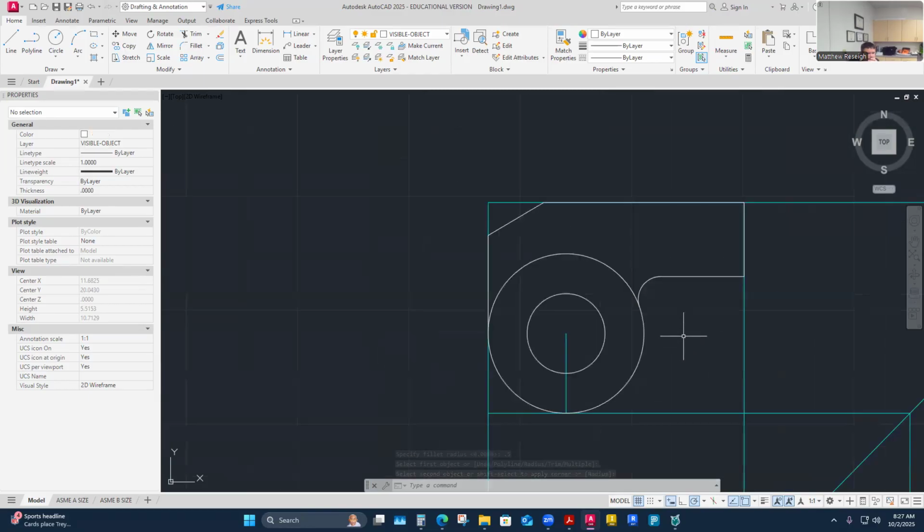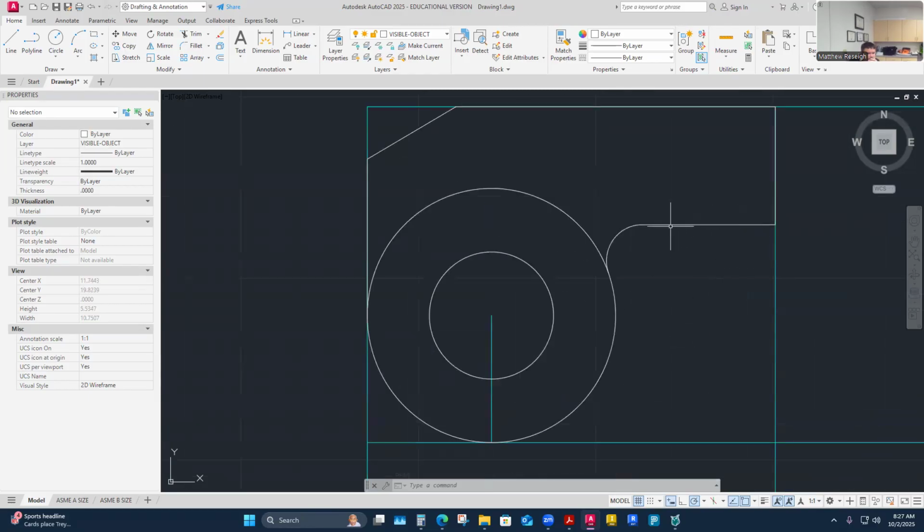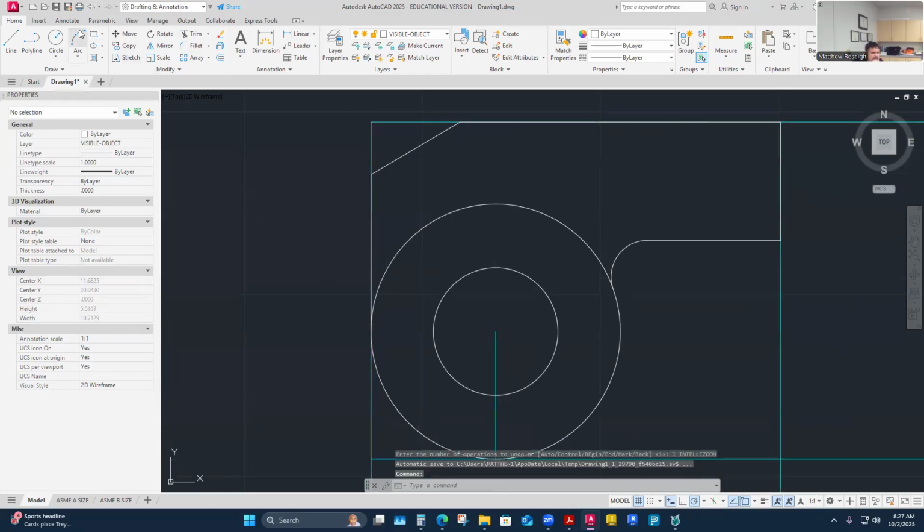So where I would hesitate on this is it really makes this like an S curve. And I feel like from center out, I should have some straight section and then pick up the radius. So in this case, I'm not going to use that. I can just tell my geometry flags are going off. This is not the way that sweeps. I need some tangent going on here. So I'm going to undo that, like Control Z, or use my undo steps.